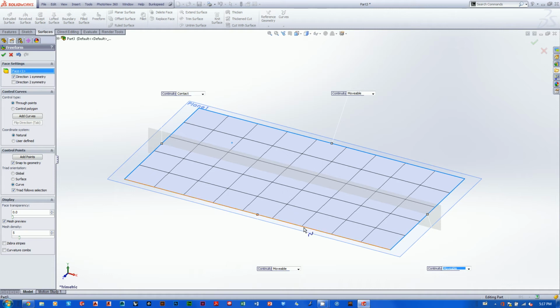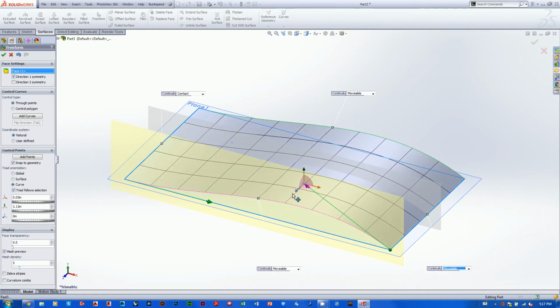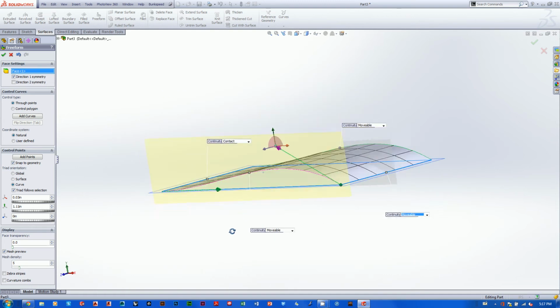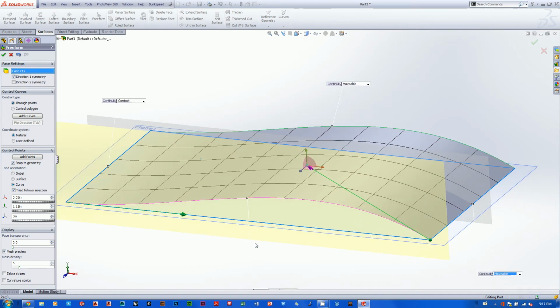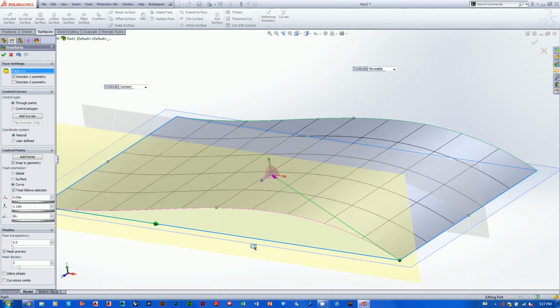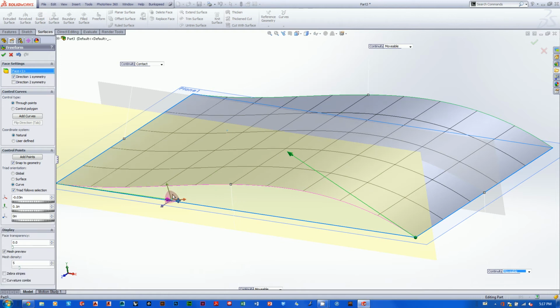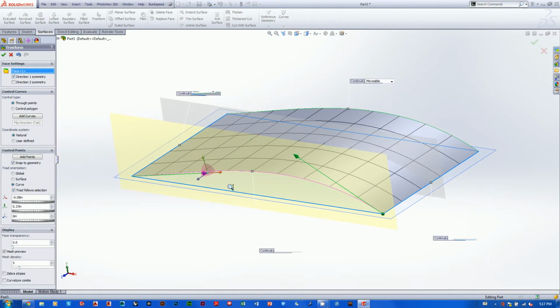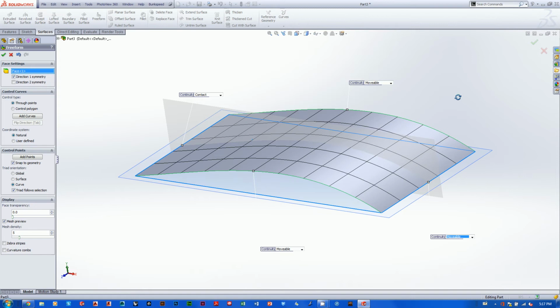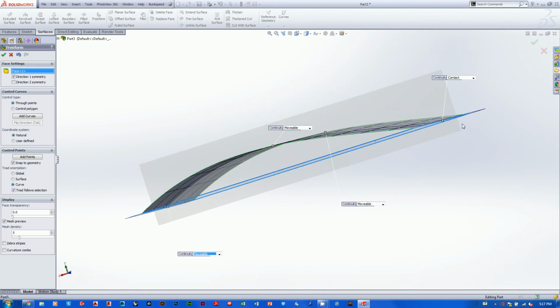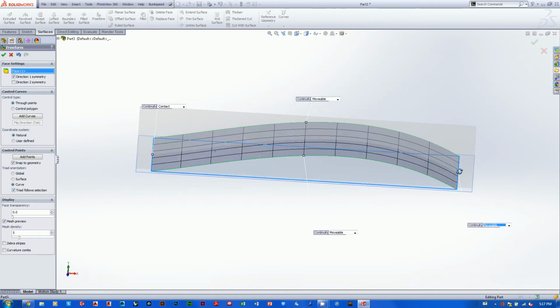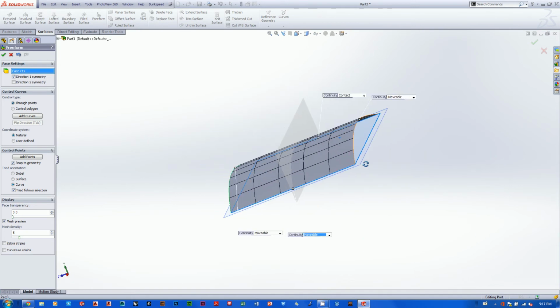There we go. Now that I've done that, I have the option to click here on this edge while I have the freeform tool open, and then I can create a nice fluid fun shape using these arrows here. So let's do that. Very good. And I'm just going to click here, excuse me, let me get that edge again, and we're going to create something very good like that. Okay, so now I've created this nice sort of arced form here, and what I want to do is bend the edges down so I get a little bit more of a pillowed shape.